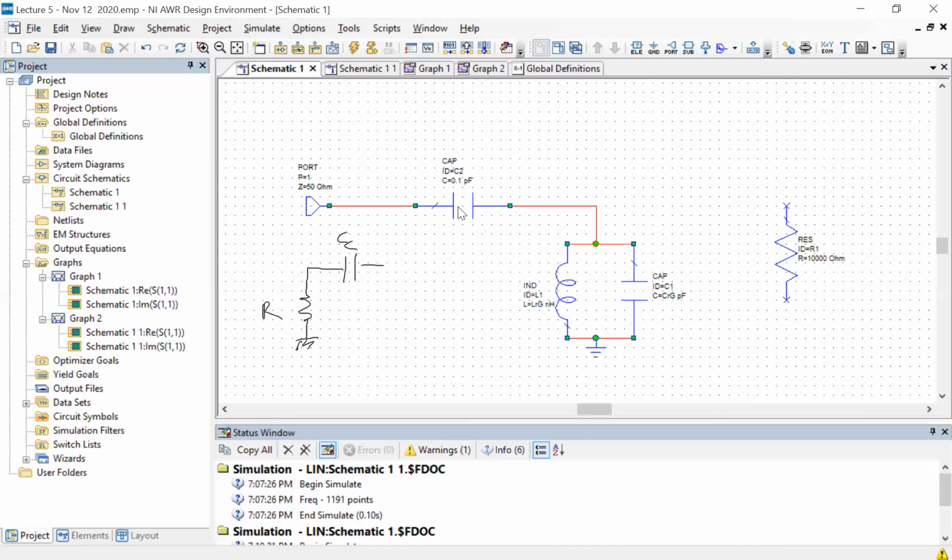Because we like simple LCR circuits coupled to the outside environment, without additional complications like this, we can make an approximation and a simplification which allows us to do two things. One is this effect of frequency loading, and second is the effect of how much capacitance to put here to go from some Q value to some other Q value. In other words, what is the new expression for Q?